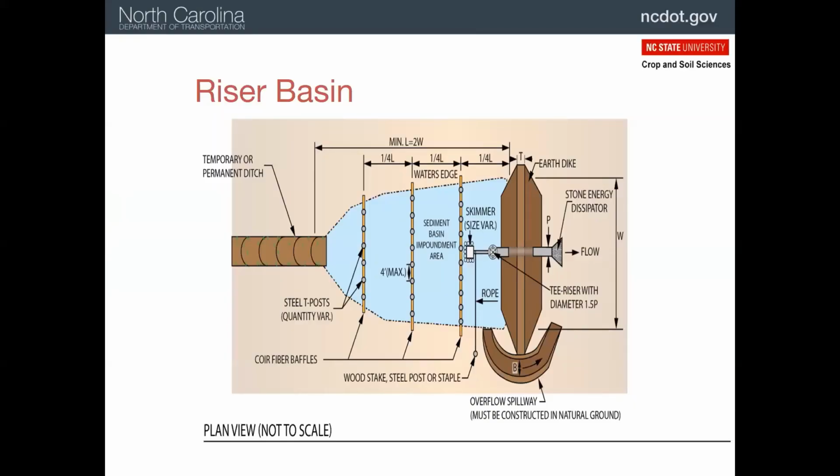And here's our aerial view where we've got the spillway here, the concrete riser or metal riser, skimmer, baffles, etc. On a stormwater basin, you're going to have some kind of emergency overflow spillway, which we won't have with our temporary basins.